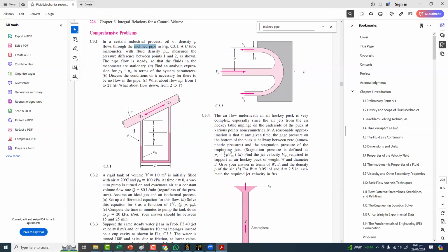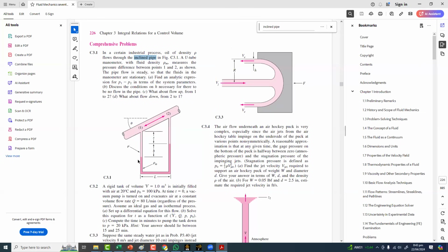So I think in this case, you can set up the problem in your CFD. You can include the manometer also. But now, if the manometer has mercury and you are putting the oil here, how are you going to model this geometry? This geometry will not be very difficult actually. You can have the mercury here. So now you have to solve the problem. You have to include the gravity and everything there. So what will be the pressure difference between these 2 points?